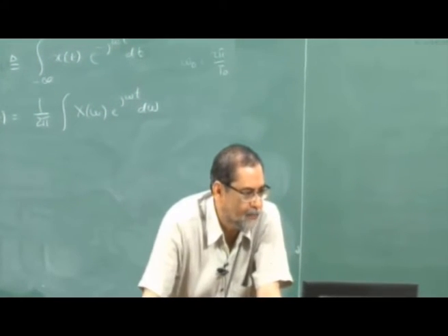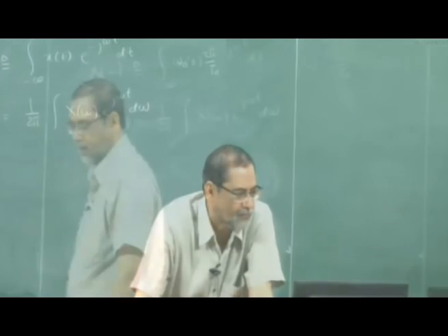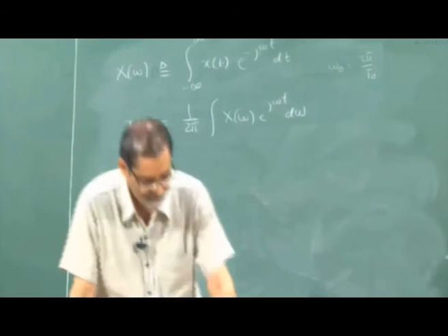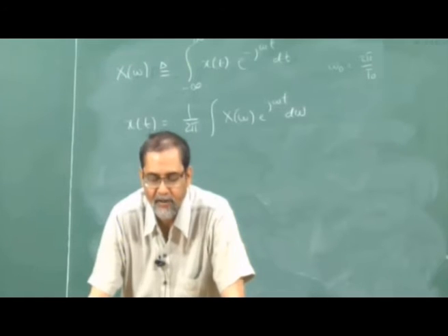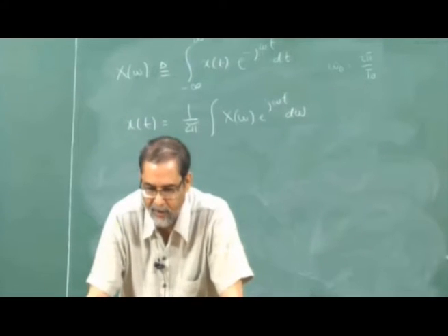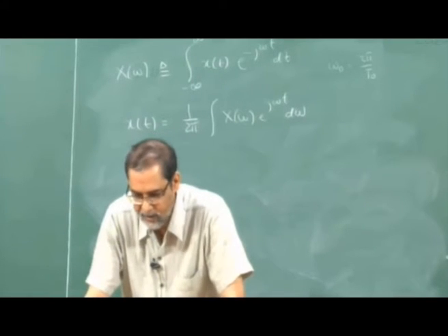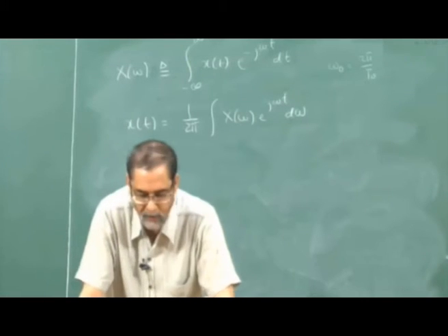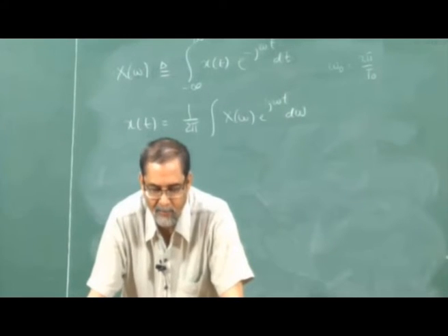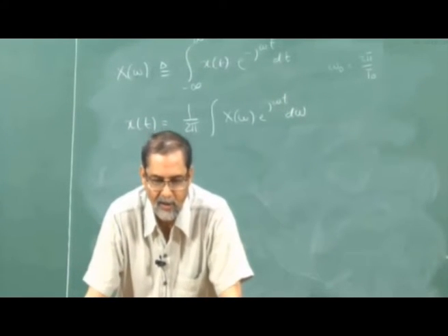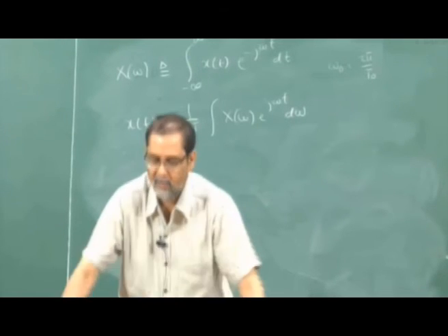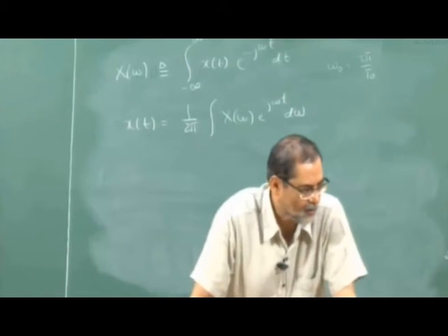Fourier series for full wave bridge rectifier is a sine or cosine waveform. You know, sine and cosine are identical waveforms except for phase. That's the point I made earlier, right. So you can take a sinusoid and full wave rectify it. You can take a cosine and full wave rectify it. I mean, final answer is the same, right. Except for some phase difference, answer is the same. So the Fourier coefficient will have an additional phase term. When you take its magnitude, that term just vanishes, right. And so sine or cosine doesn't really matter.